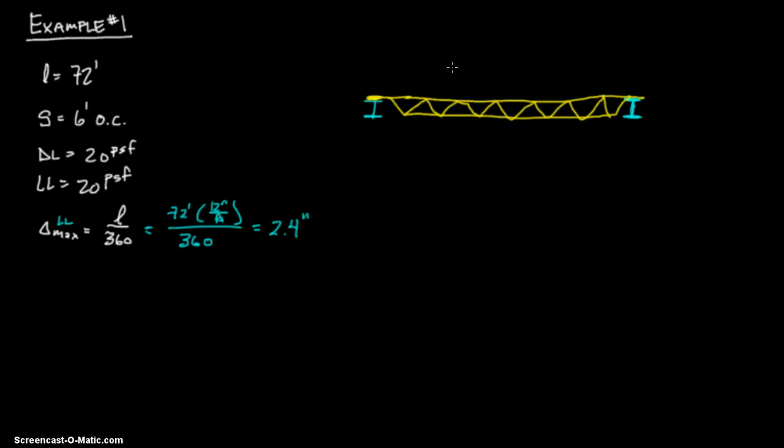You'll see these, and they're cheap because they are standardized. They can mass produce these things, and that's why they're cheap. They don't have to specifically design these for each one. They're similar to typical wood beams. They just pop it out, and there you go. They're simply supported right there, and they'll tell you how far you have to brace them, like bridging. You have to put bridging on there.